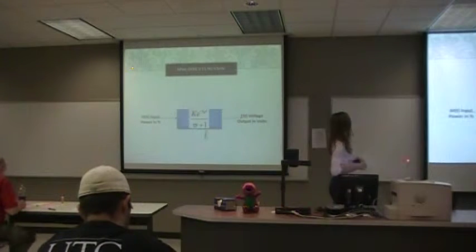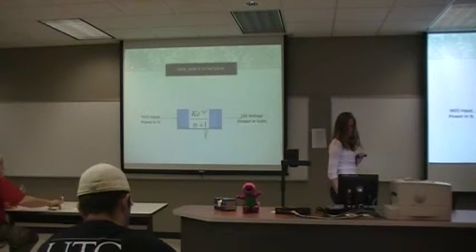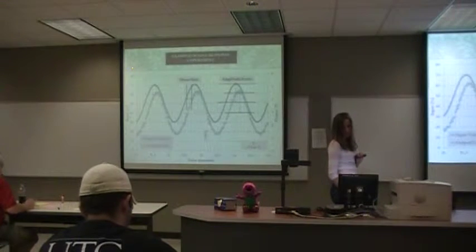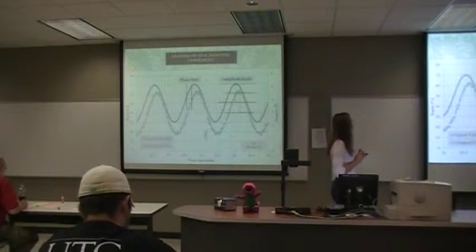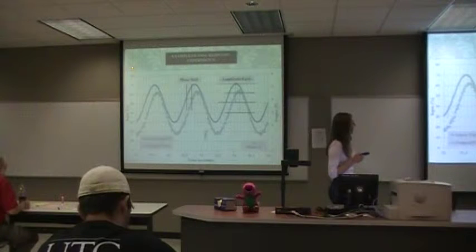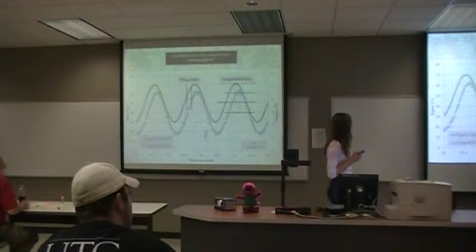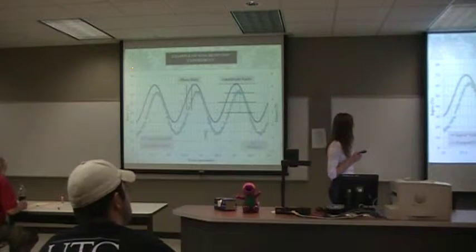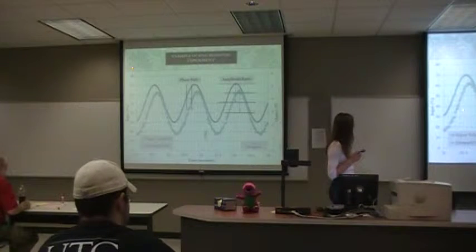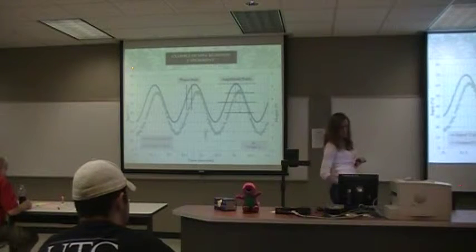So for the sine input function, here's our input function, transfer function for it. And here is an example of our sine response experiment. You can see where we will want to calculate the phase shift and the amplitude ratio. This darker blue is the input, and then the lighter blue is the output.